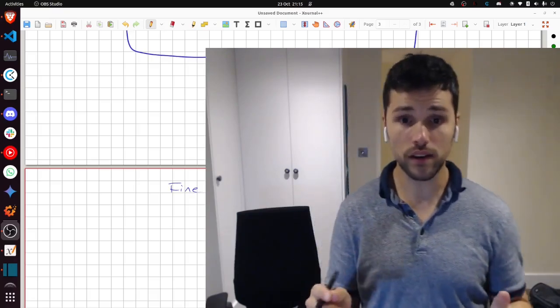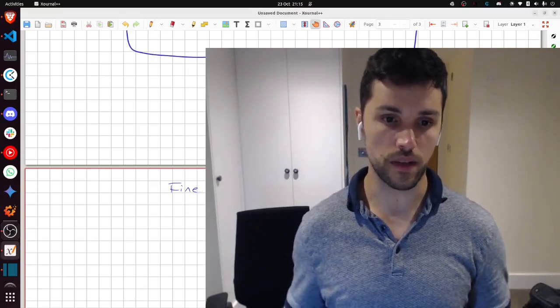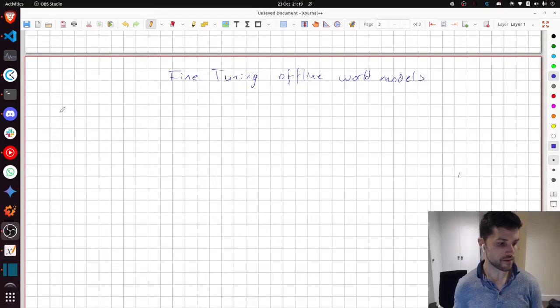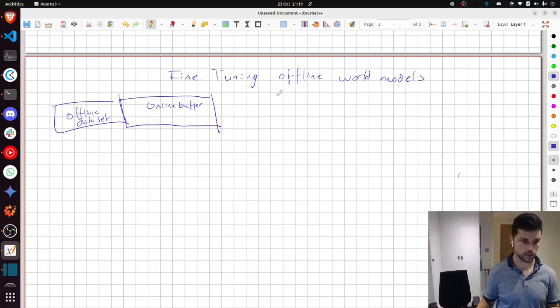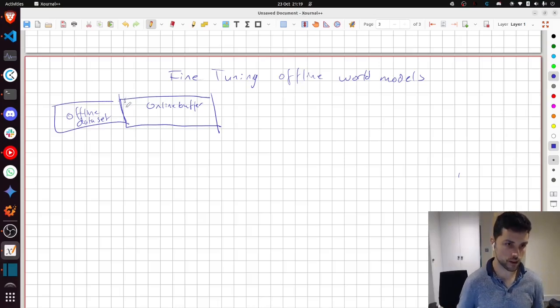And then there's the online training loop, which is a bit different. So we have this offline data set. And then what we have to have is an online buffer of some capacity, where this is empty at first, and then after we've done the offline portion of the training, we run, say, 20 rollouts of the robot. We make it try to do the task 20 times, and we record that each time. And that fills up part of the buffer.